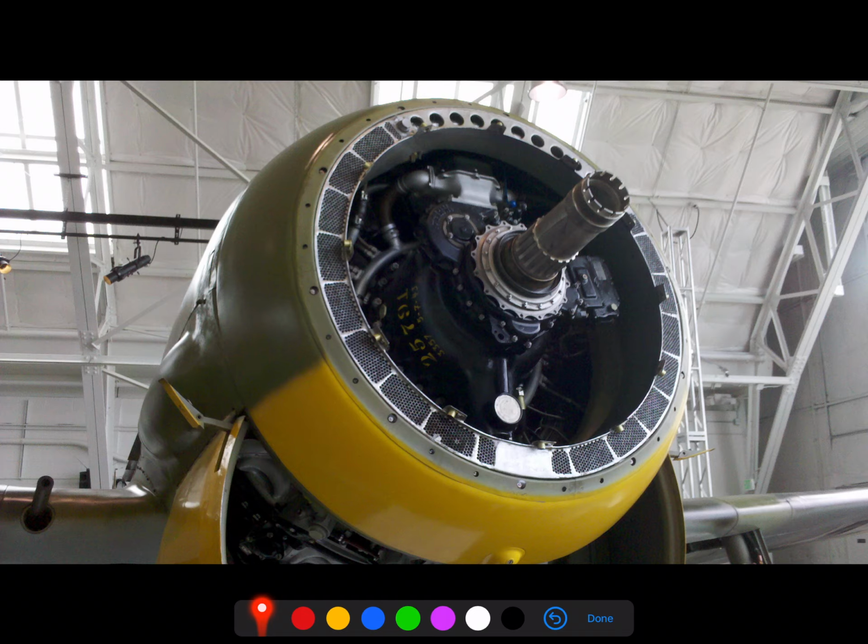Now let's take a look at how this is going to function. So as we look, here's our nacelle portion right here. We have our oil cooler ring, which goes all the way around the front end of the engine nacelle there. And then we have the armor plate, which sticks right over like so. Now I've drawn that with a gap intentionally because there has to be a gap between that armor plate and the nacelle of the aircraft there.